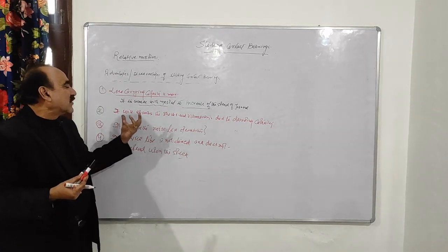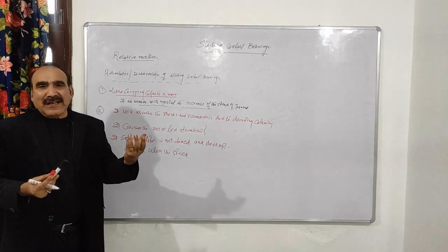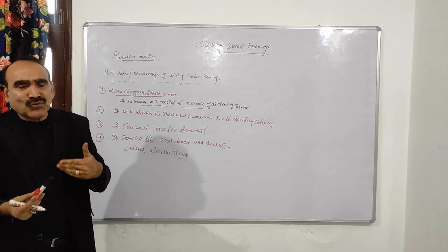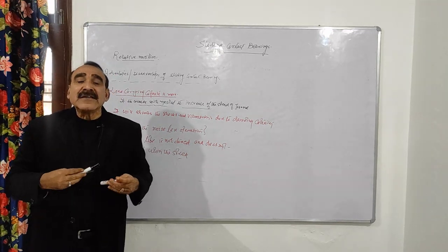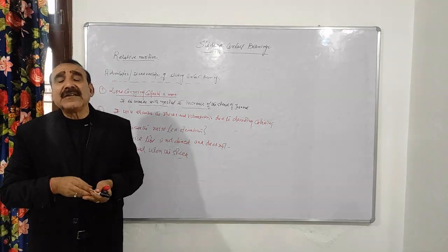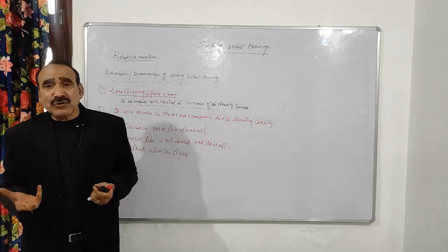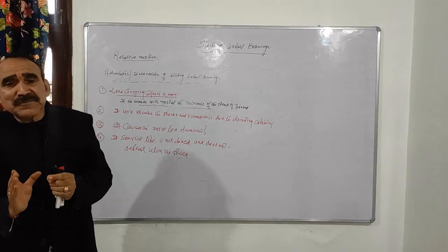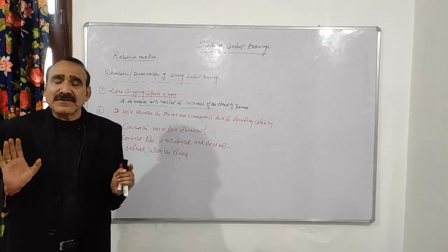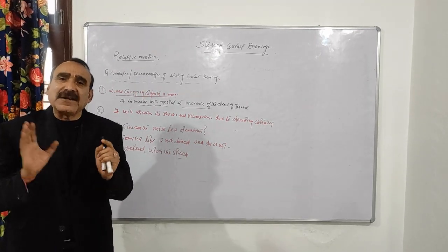थर्ड, you can say इसका ऑपरेशन जो है noiseless होता है, तो इसका ऑपरेशन जो noiseless होता है उसको मैंने आपको explain किया था कि किस तरीके से होगा कि in most of the bearings, you can say in hydrostatic bearing, in hydrodynamic bearing and in journal bearing, lubrication plays a very important role here in case of sliding contact bearing, right?